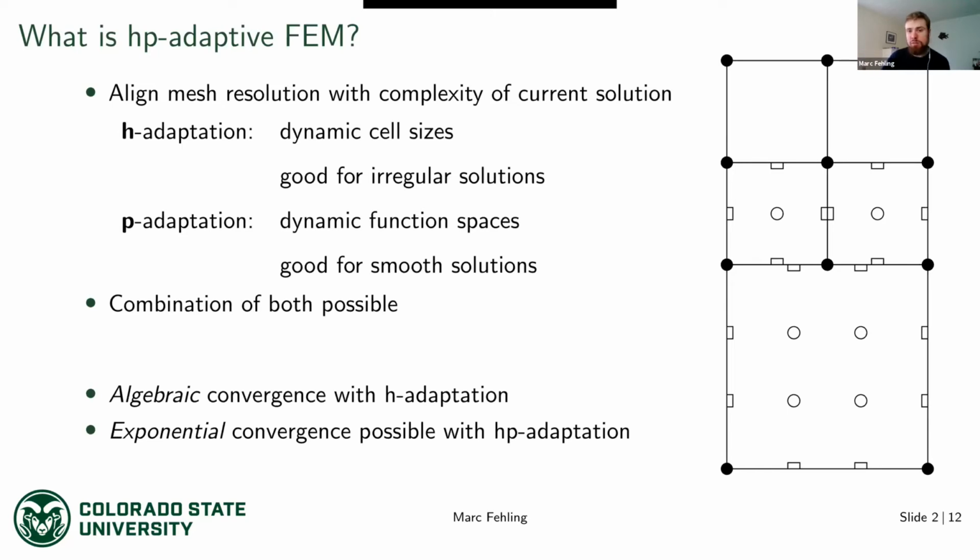So the top half of the mesh is h-refined, so you have an h-refined cell. And the bottom cell is represented by a higher order finite element. The little dots here represent nodes on that cell. In particular, this should represent a Q3 cell, for example. So you can mix both approaches with that.